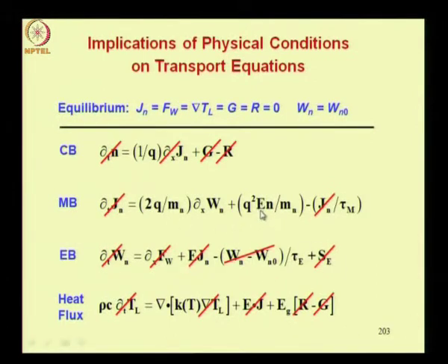So you see for a non-uniformly doped semiconductor E is non-zero. However, since other terms are 0, these two terms should sum to 0. So therefore it shows that there is a non-zero spatial gradient of kinetic energy density. Now as we will see, this is due to the presence of the carrier concentration gradient, and that is causing a diffusion current.